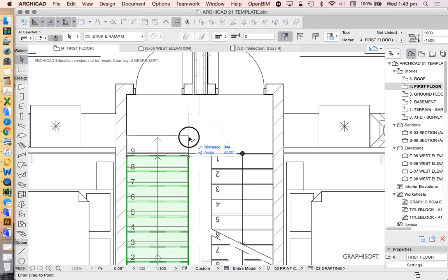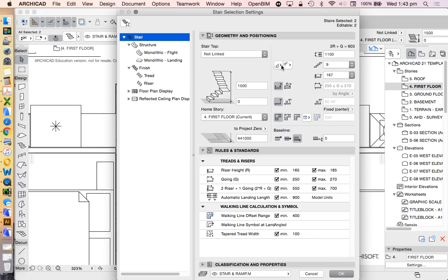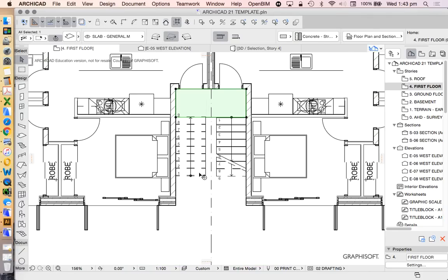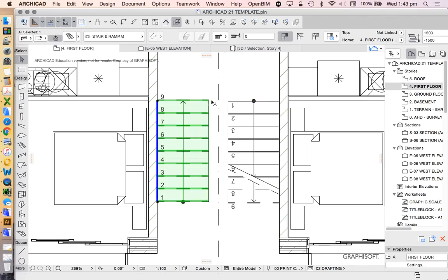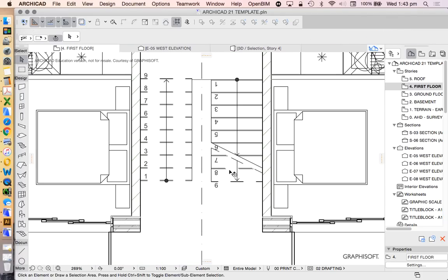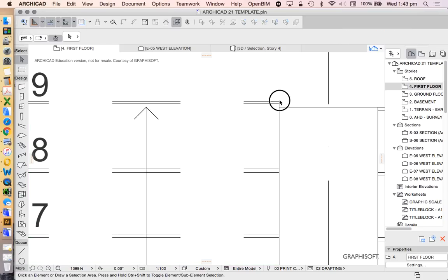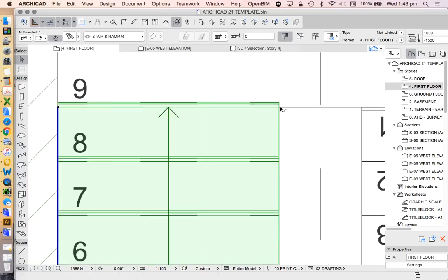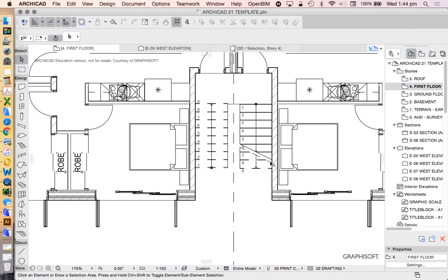Now when we're creating stairs, how do we make them? My preference is these options here, that we start with the riser and we end with the riser. That means that we make our slabs or our landings do the rest of the work to join it up. I think that is the most practical way that conforms with the way that our stairs work in terms of an Australian standard. And we see that's overlapping here, and that's because what we're not seeing is the nosing. So we're allowing for our nosing to line up with the landing, not necessarily the back of our tread, in case you're wondering why that's doing that. That looks a bit odd.